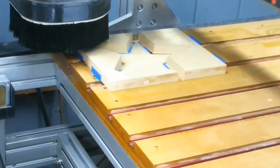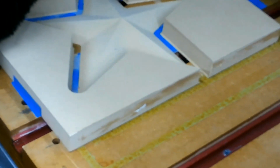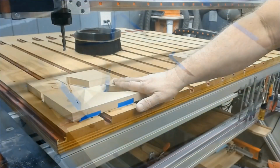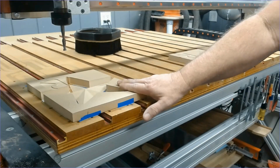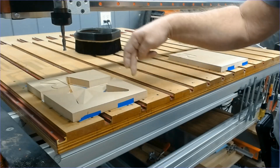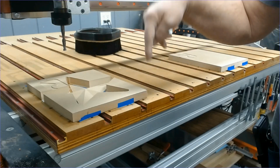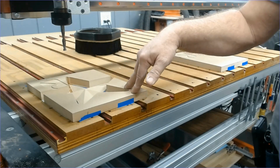And as you can see, it cut through the material just fine, leaving that blue painter's tape firmly attached to the spoil board. This is a good demonstration of why it's a good idea to set your Z0 off of the machine bed when you're using a profile toolpath to cut out a part.